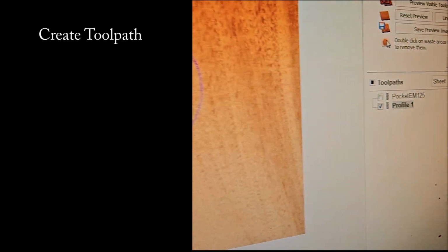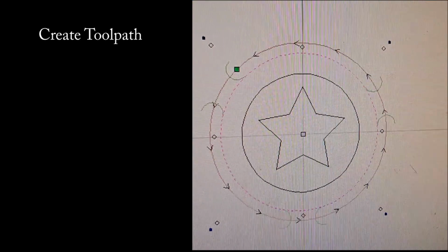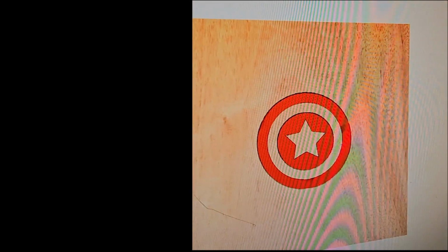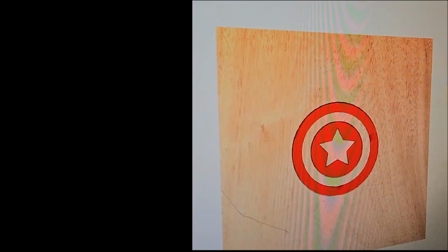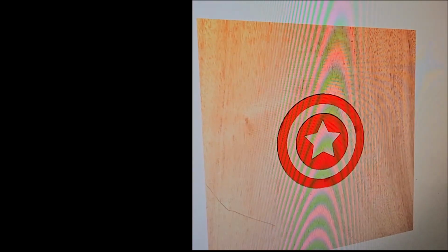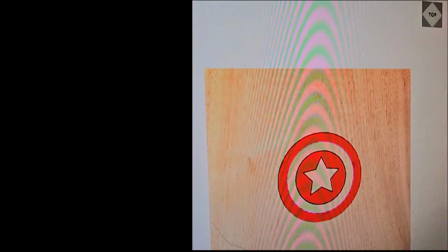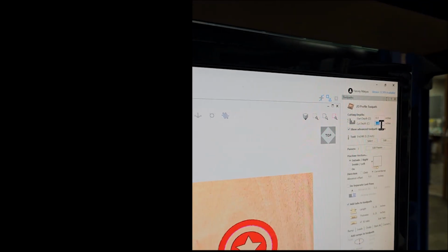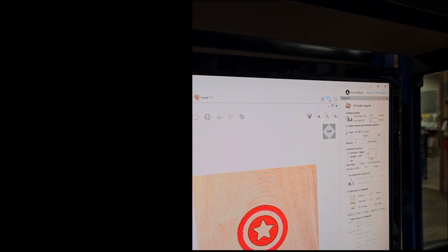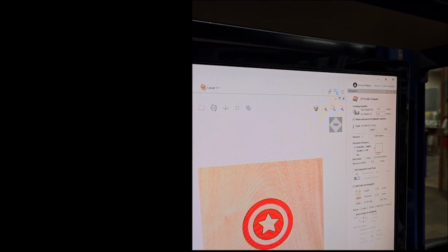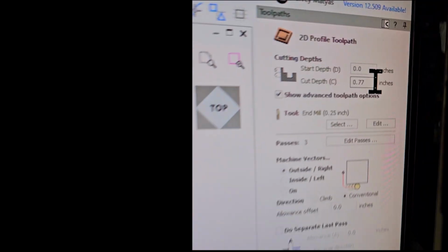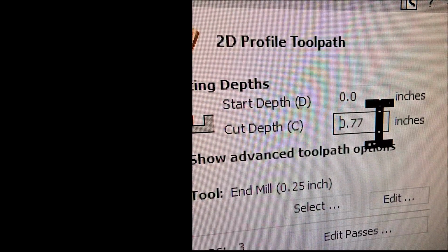And there it is, the calculation, and we can preview the cut. We didn't go deep enough. We only went 0.05. So to cut all the way through, you do Z plus 0.02 equal. So it's going through the thickness and adding 0.02 inches to it.